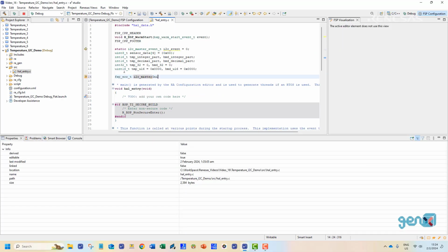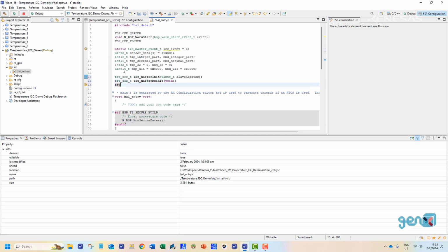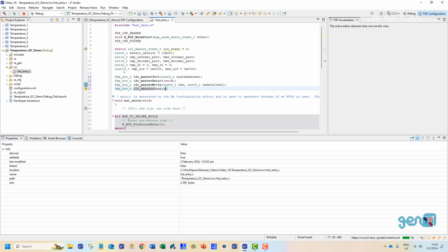We will then declare the function prototypes for the various operations of the I2C module. There are 2 functions for initialization and deinitialization of the module, and there are the read and write operations. Each of these functions involves calling various APIs and error handling for successful data transfer. Designing these functions basically constitutes designing the I2C driver.